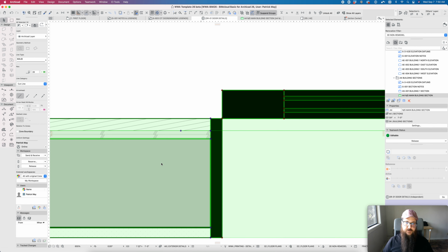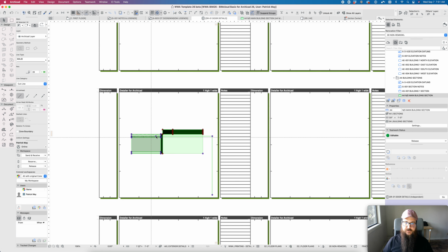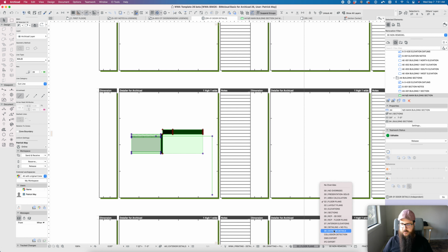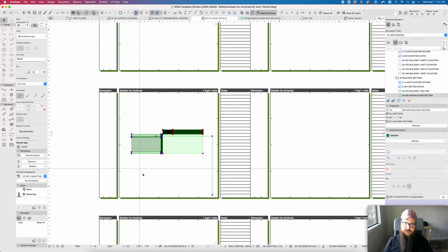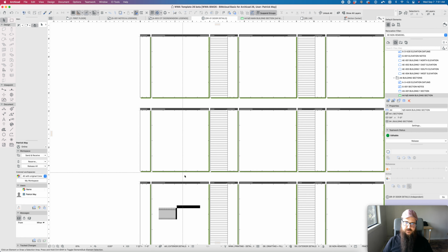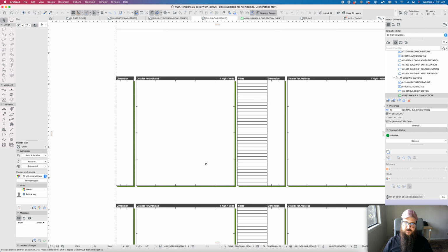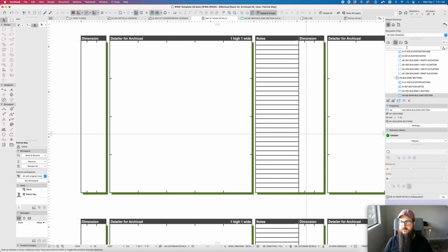That makes a few changes right away. I can see that the fills automatically generate their fill color for some of those hatches. The model view options are not too terribly important. I can say that these have a fill. That's sort of an antiquated setting there. The graphic override, same thing. I can say that that's exterior details, non-remodel, fractional feet, and inches. So these are all the view settings for generating this detail now. And I can start creating details and mocking this up before I've even drafted anything, really, which is sort of the nice thing about this system.